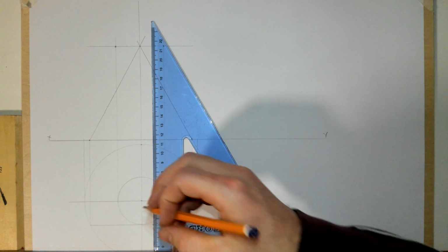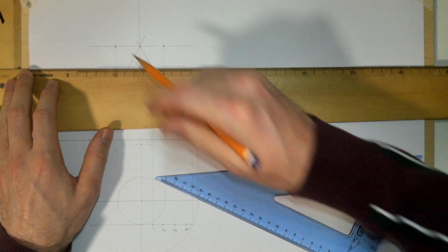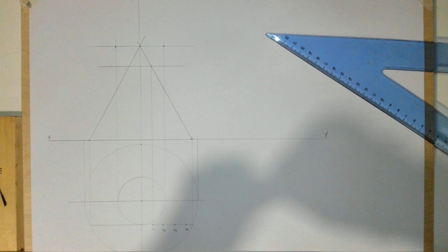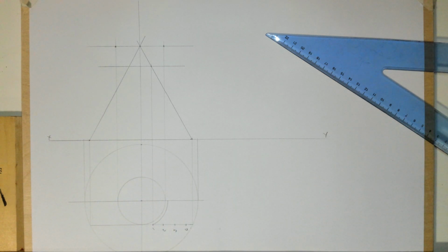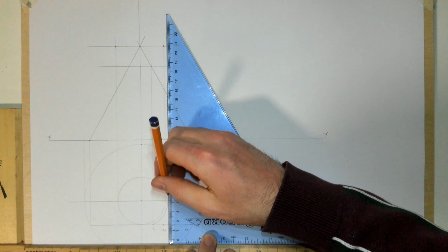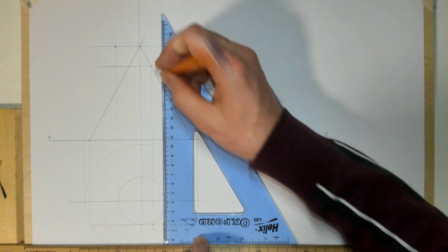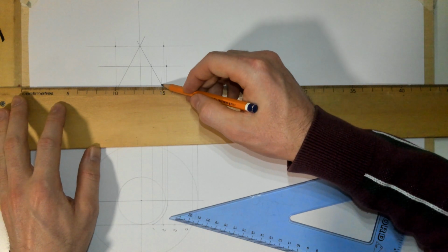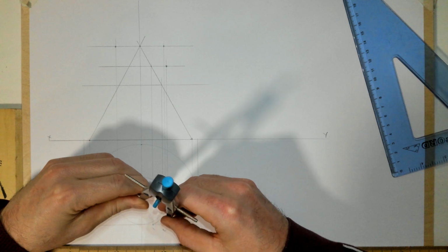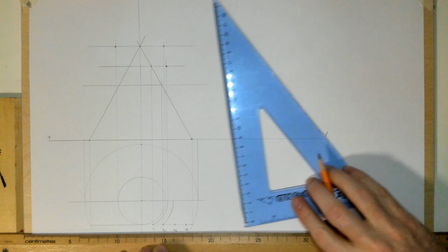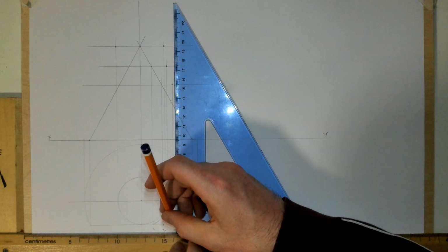Each one of those points now will come up to the asymptote line, which is there, and then come straight across. And then in plan view, I'm going to swing it around at the center point, set my compass to 1, swing up to the horizontal line, and then bring it straight up to the front elevation, to where it crossed that line that I brought across. Okay, same for each one of the points now. So bring 2 straight up, where it crosses the asymptote line, bring your line across. Set your compass from the center to 2, scribe a line up to horizontal, and bring it straight up to the front elevation. Okay, same for 3 and 4.